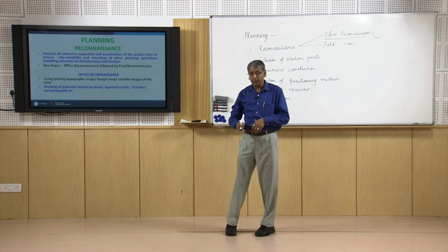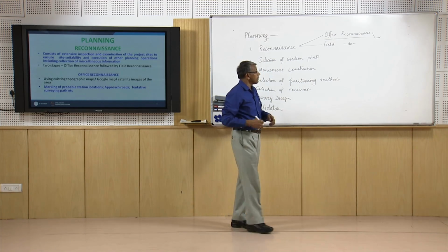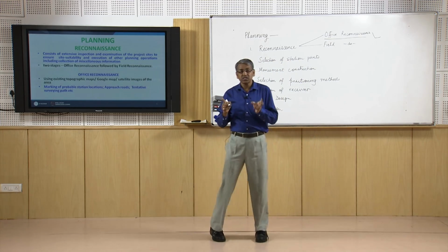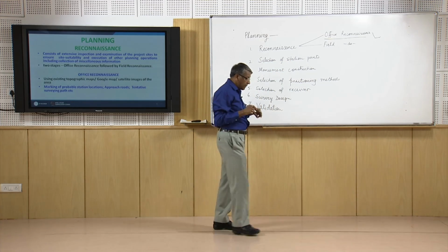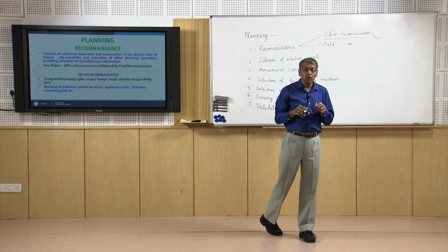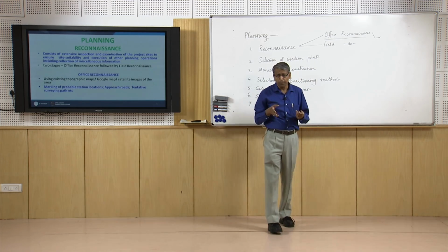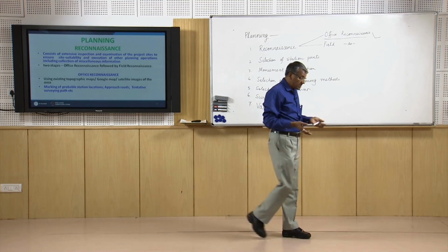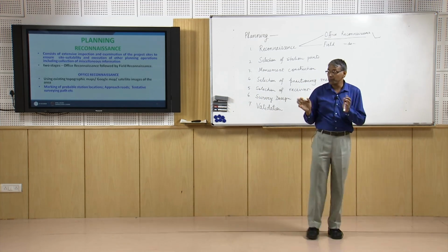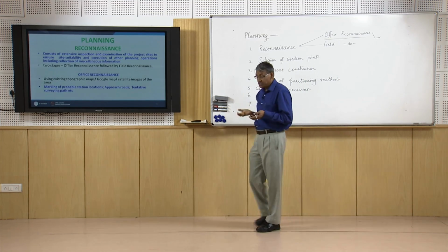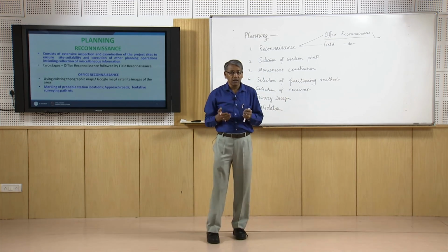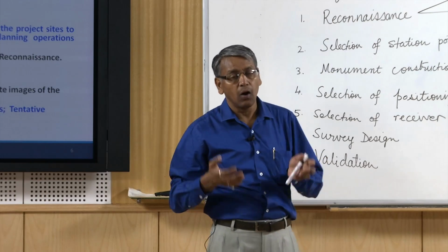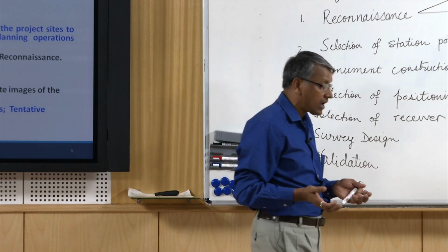From the topographic map we try to find out the possible locations where stations may be established, and also we look for the possible routes through which we have to go to the site, and then possible infrastructure, like where to stay and how to communicate to the project area.